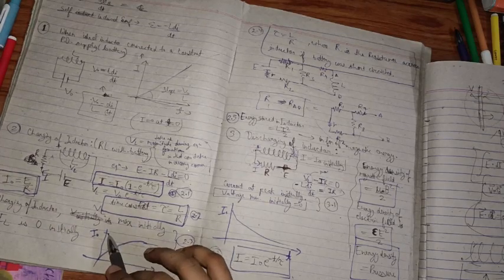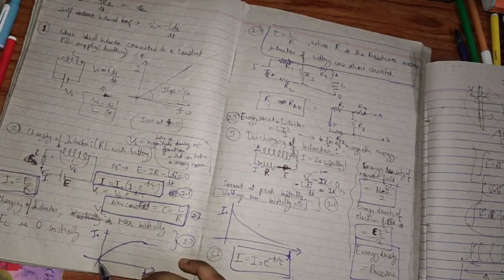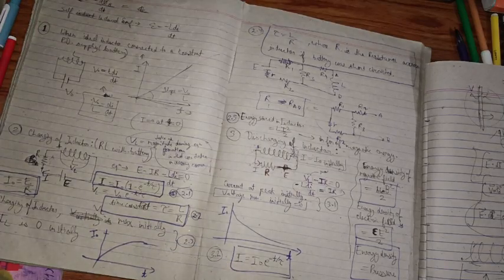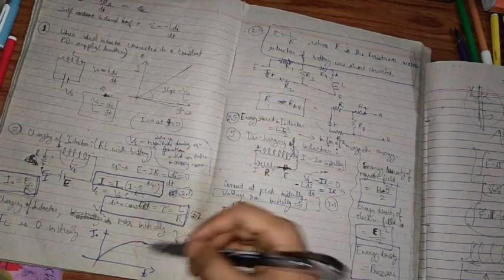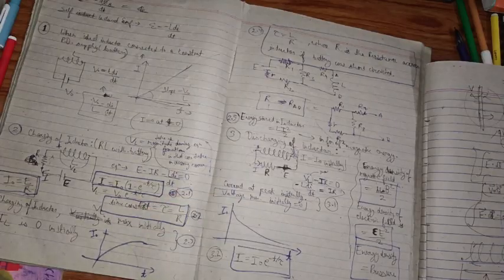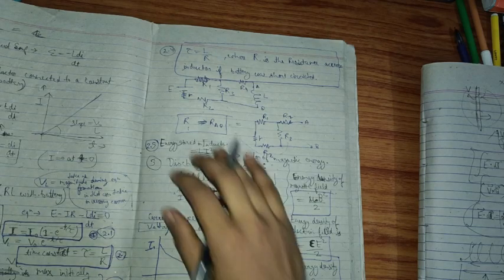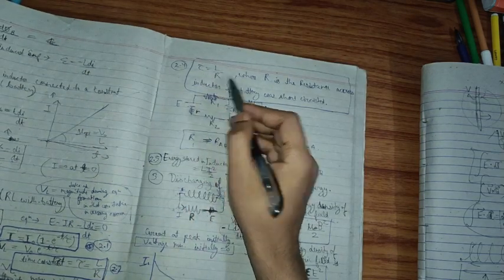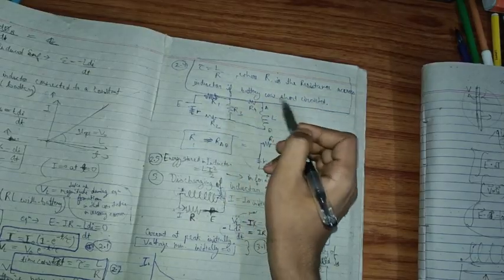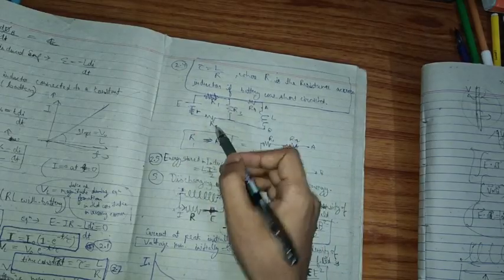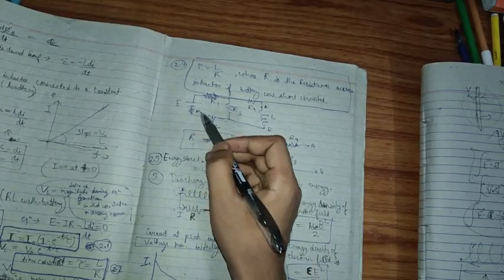So in this case, let's take one example for this time constant L by R, where R is the resistance across the inductor when the battery is short circuited. What does it mean? Let's take an example where we have a circuit like this, an inductor here and a few resistors. Now if this is short circuited, let's say this battery has some internal resistance R, so we will include this internal resistance but remove the battery and short circuit it, and have the same circuit as before. Now the resistance across this inductor AB, R_AB, we have to calculate, and that would be equal to the R we have to use here.